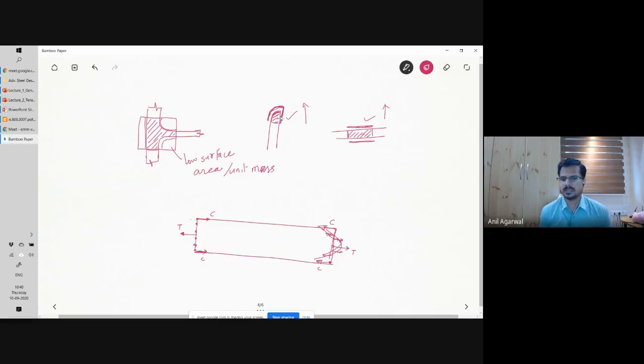And actually, how you measure this is also very easy. Basically, what you do is you take a beam. You see, this is the beam. You have a long beam, whatever, like 2 meters, 5 meters, whatever. Then what you can do is you can attach some strain gauges to this. The strain gauges should be oriented along the length, but they should be placed in the width direction. You understand, right? So this is the width direction. So you put them at the same location along the length, across the width. 1, 2, 3, 4, 5, 6, several of them you can put.